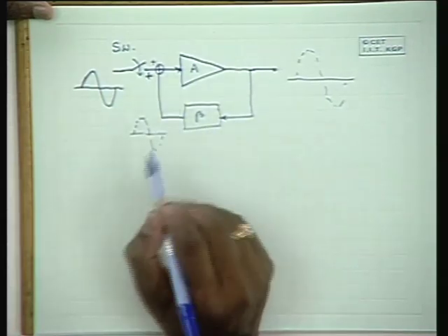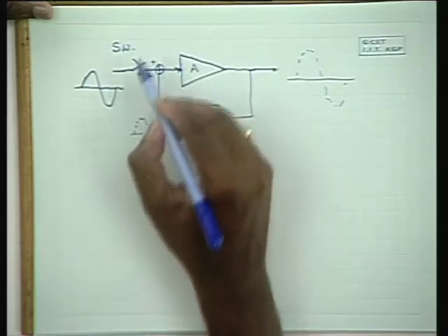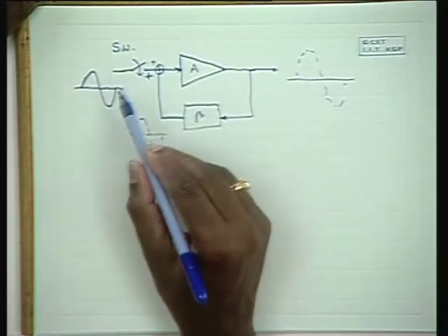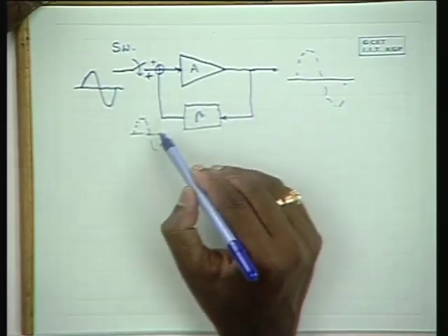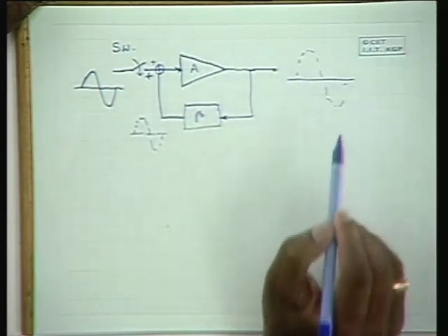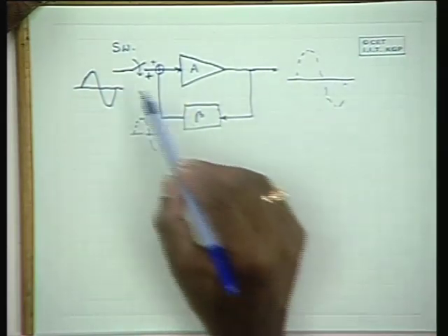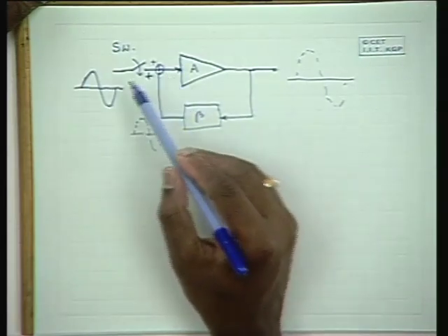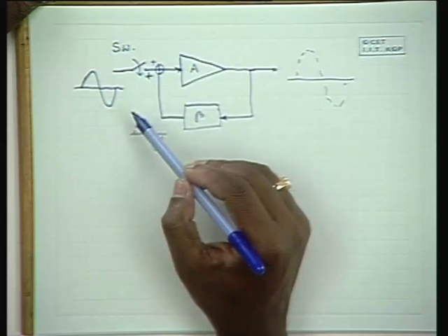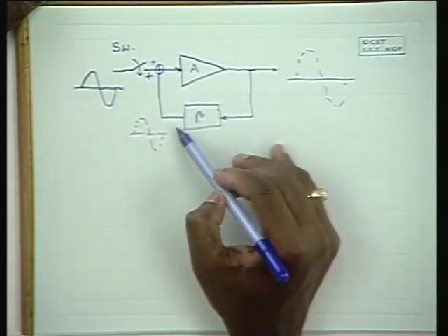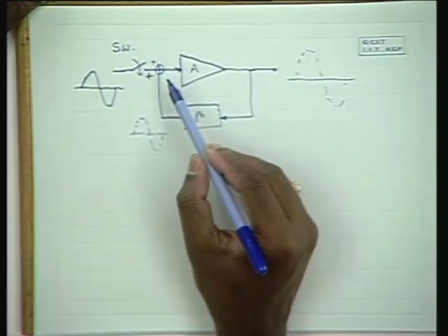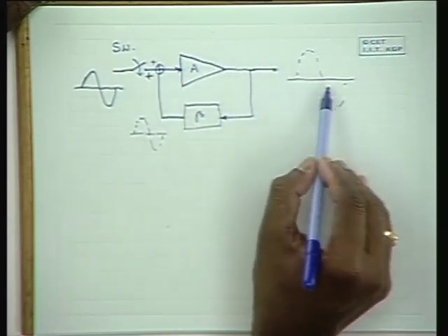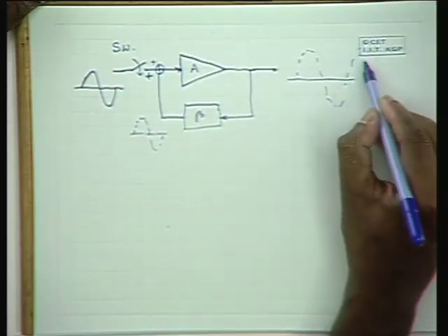So, when this goes to the input, and if the feedback is positive, and if I open the switch now and do not allow any other input, can this feedback voltage sustain the output? One cycle has gone and come back here, and I do not apply the next cycle, but this cycle which has come back acts as an excitation for the next cycle, and the second cycle will be produced.